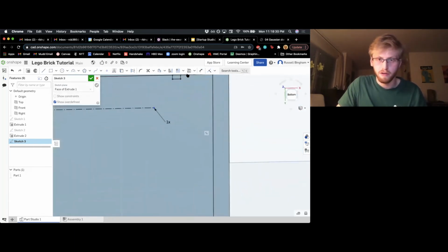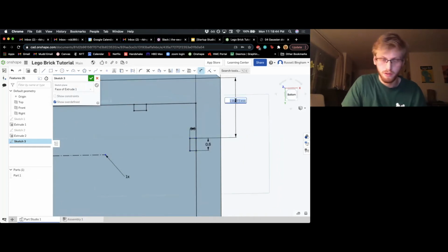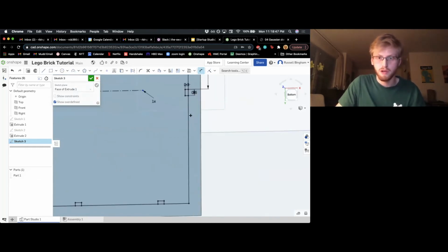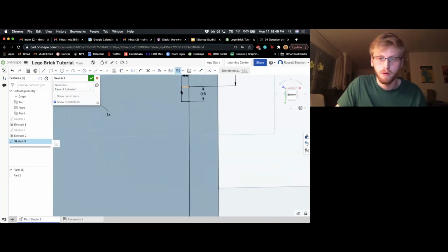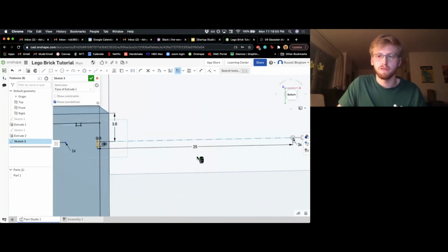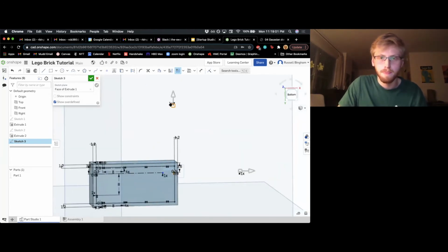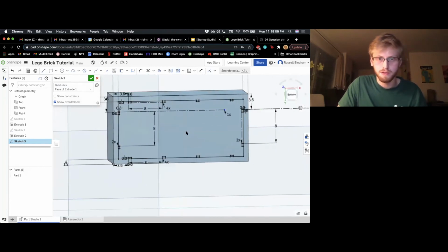Same thing again over here, exactly the same process. Make a rectangle, a single instance of the object we want, and then have it be in the right spot, and then repeat it in the direction we want it to repeat. So this is again 3.6 millimeters, and we're going to pattern each of these. We've got to tell this to only make patterns in the vertical direction. And again, in the opposite direction. All right, so that's all of our nubs taken care of.